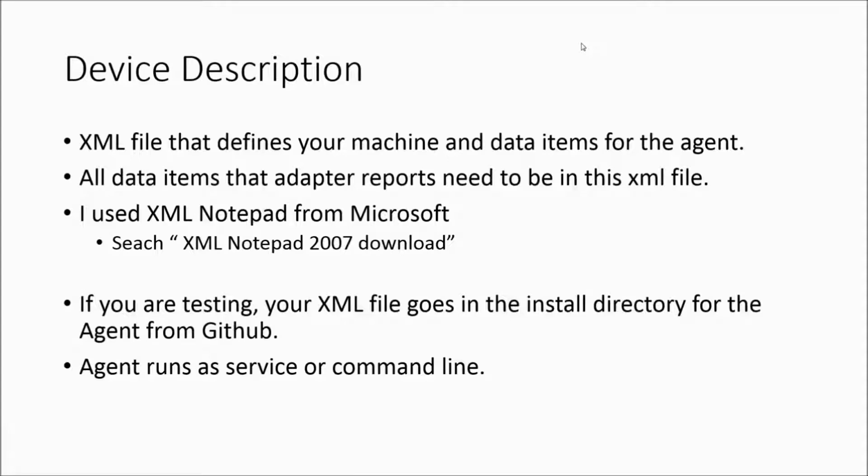The agent can run as a service on your computer, or it can run in the command line. It uses that XML file, and then there's one other file you edit, a config file, to point at the IP and the port number of your PLC.